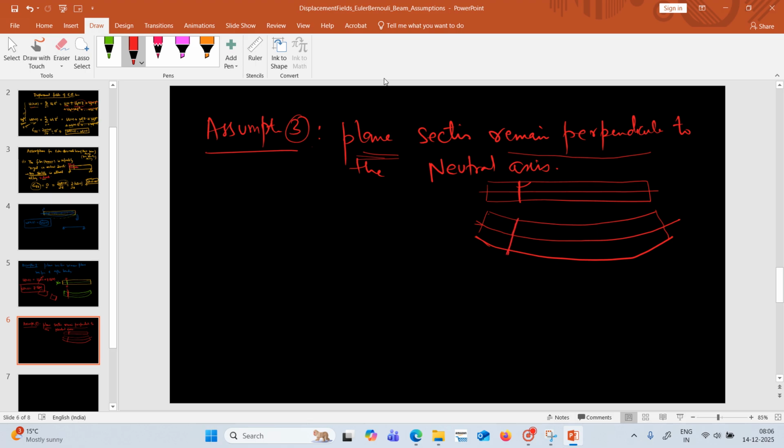So if you make a tangent at this point to this curve, to this displacement field, this curve is what? The neutral axis representing the w naught of x. That is, the transverse displacement is represented by this curve. Now if we take this tangent at this position, what does it imply? Tangent to this position with the x-axis is the theta rotation. So it only remains perpendicular, so the shear strain gamma xz equals 0. There is no shear strain. It is purely bending.